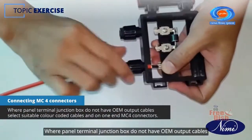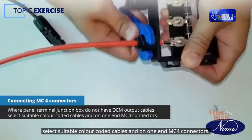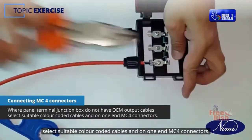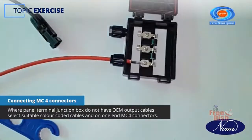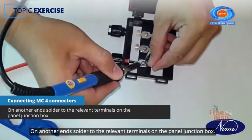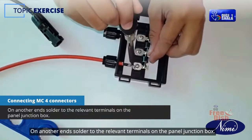Where the panel terminal junction box does not have OEM output cables, select suitable color-coded cables and on one end fit MC4 connectors. On another end, solder to the relevant terminals on the panel junction box.